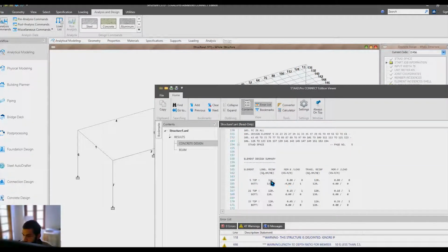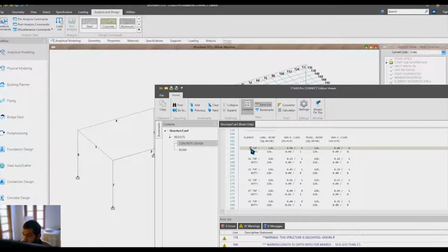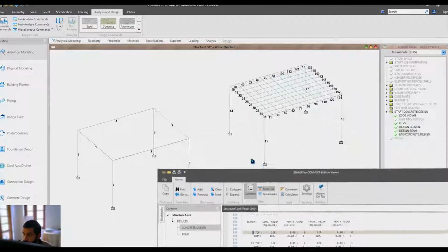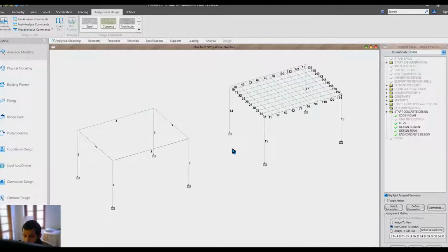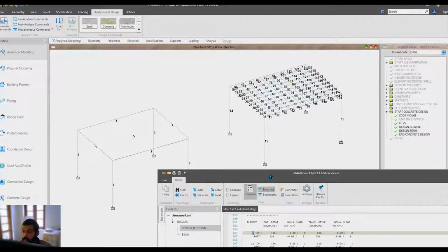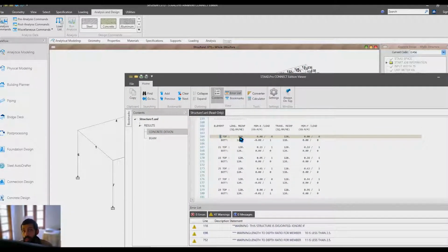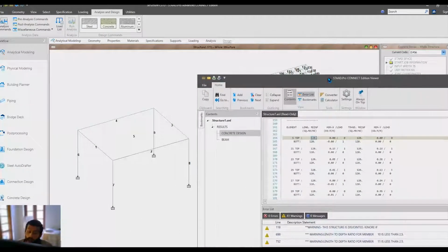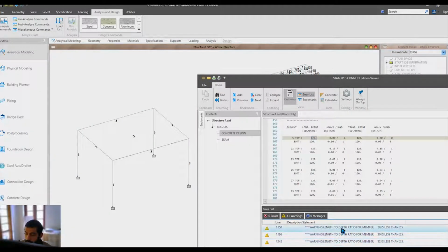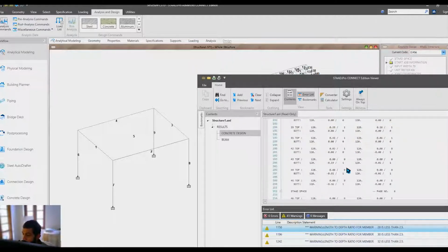So what is this? This is the area of slab. The element 5, so let's see the plate element 5. Shift and P for plate number, element number 5. So this is element 5. We are hoping for a proper design result for that element. If we didn't mesh it, the design of the slab will be there, but how the surrounding structure behaves with this slab will be a slight issue that's shown as a warning. Okay, the longitudinal reinforcement and transverse reinforcement are alright.